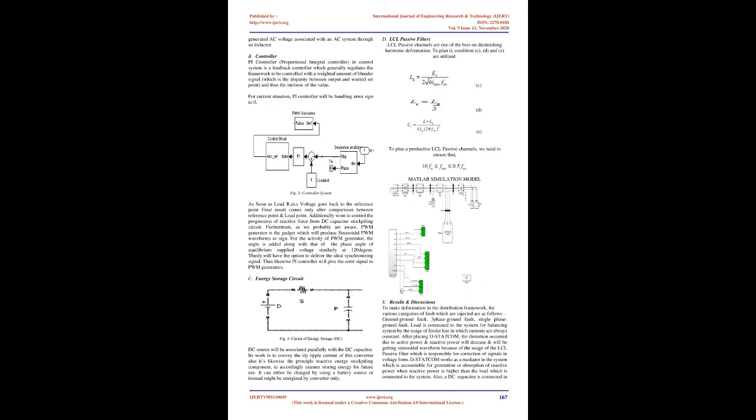These are also used for surge impedance compensation, to compensate a long transmission line by dividing it. They are also used for load compensation, wherein they maintain constant voltage, 1, under load rejection and outages of generator and line, 2, under slowly varying load change, and 3, under rapidly varying loads. Overall they improve the stability of the system as well as the power factor of the system.